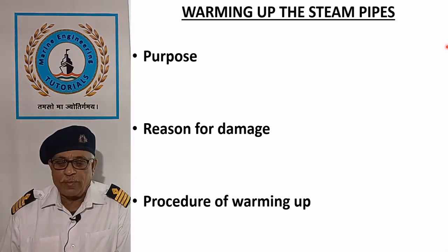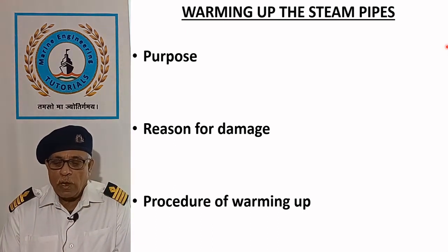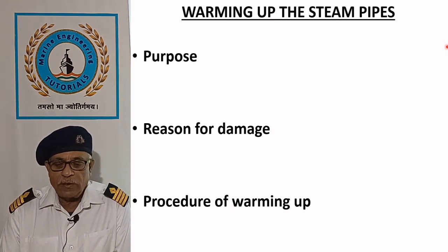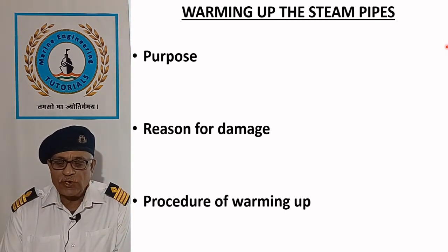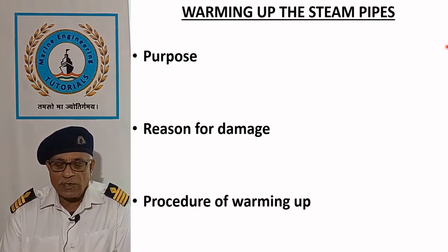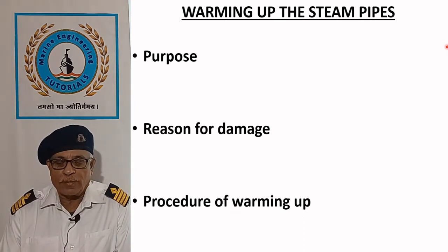Procedure of warming up. A number of drains are provided in the steam pipe at various sections, which should be left open when the pipe is not in use. Drains are most essential for removal of condensate from the steam pipe during the startup.